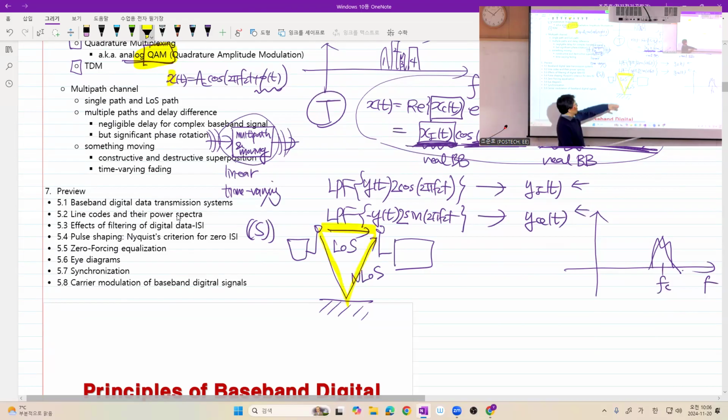Of course, the motion of such an object in our radio propagation channel may be slow relative to our data transmission rate, right? It's not like the bus serving as a reflector in my radio reception moves at the speed of light. It moves around 60 kilometers per hour or 30. However, if we use a carrier frequency high enough, a little bit of time difference, a delay difference, may give us a huge difference in phase change.